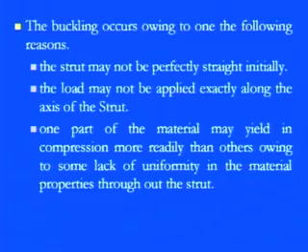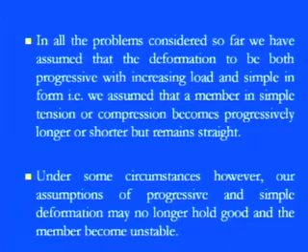So these are the three reasons, in which we found that it is more on the geometry, so we can say it is a geometric nonlinearity, or more on the material, so it is a material nonlinearity. And the third part is when the force, or the load action, is not along the same line. So if you're talking in a general sense, these are three of the key parameters through which we can say there is a great chance of having buckling in the strut.